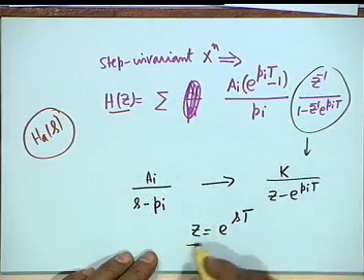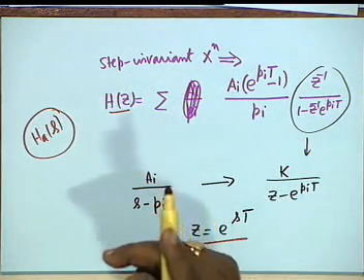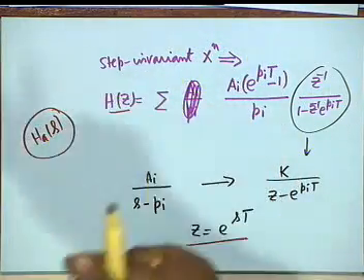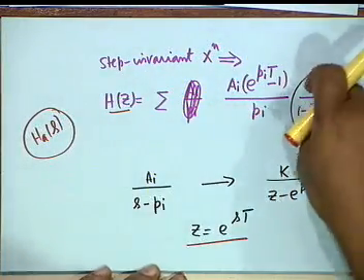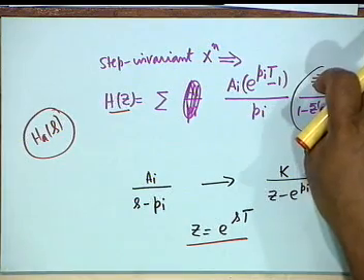Yes. So the transformation is the same. If the transformation is the same, how come the transfer functions are different? Yes? The answer, isn't it obvious, the answer? What was the term in the partial fraction expansion of H(z) obtained by impulse invariant transformation? Was there a Z inverse in the numerator? No. That is the only difference.